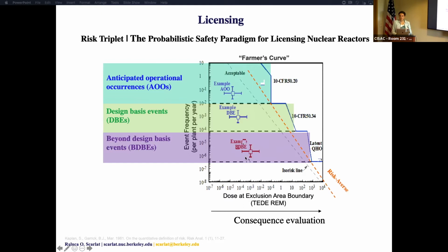The low pressure operation of a molten salt reactor system makes it much easier to make the case for low consequence of events. If there is no stored energy available to disperse radionuclides because the system is operating at low pressure, then we would expect that scenario of a vessel breach or a pump shutdown to be quite far away from the limit of